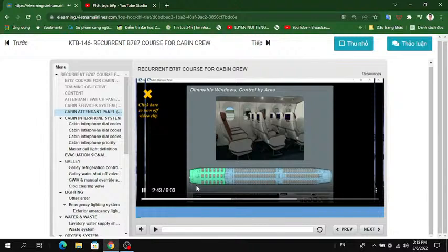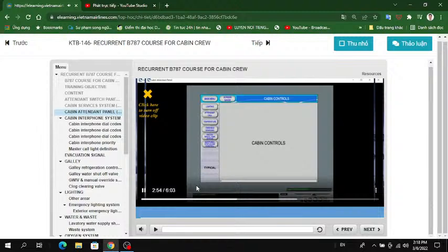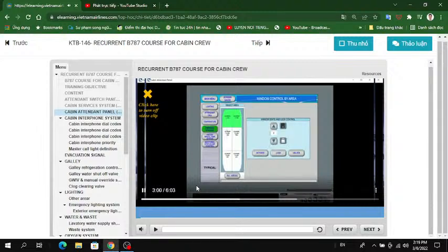Flight attendants have control of the dimmable passenger windows. Windows can be controlled by cabin area or by window. Select Dimmable Windows. Select Window Control by area. Window State and Lock Control allows setting a single level of dimming for windows by cabin area. Clearest range equals 1, and darkest range equals 5. Let's try that now. Set the dimming level to 1. Select Activate.